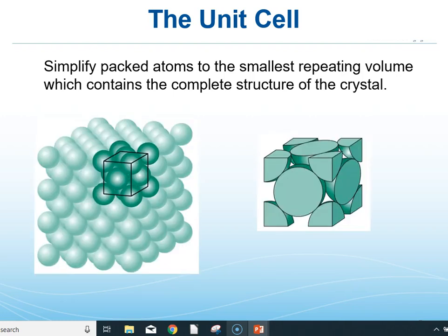So here's an example of a unit cell for a face-centered cubic crystal. You can see the whole crystal in grayed out form over on the left, and then the darker representation, just what is in the lines of the box. Not the entire series of dark spheres, but only the atoms that are within the box. As you can see, we're whacking them. The face atoms, only half belong to that unit cell, and on the corners, only like an eighth.